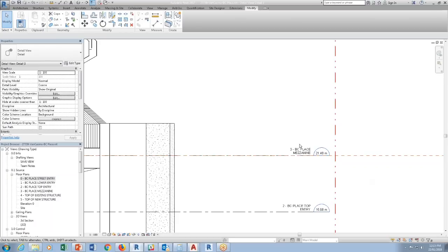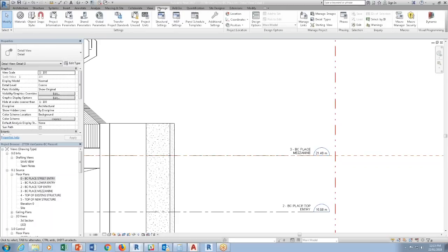But one thing you have to be aware of is that if you are using a lot of keynoting, this thing will just keynote to that property line. There's no workaround at the moment, but I'm still finding out if there's a way. But if you're doing a lot of design development, you want to know exactly where your property lies and your relationship with your building, this is the way to go, rather than just drawing in your own line. So, any questions so far with this?